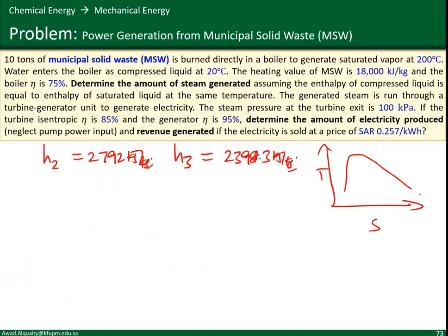the Rankine cycle. This is state 2. The vertical line will give you 3s. This is 3a or 3 because of the increase in entropy, and then we end up with state 4 and 4 to 1. We are not considering the 4 to 1 process, but the 1 to 2 process is considered in the boiler. 2 to 3 is the expansion part. Okay, we're not even looking at heat rejection. So now we have S2 and S3.